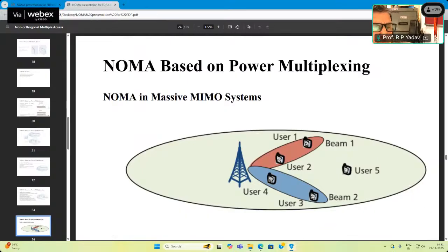And these MIMO systems help us in ensuring reliability. That means the signal will reach more reliably with the MIMO system, because the antennas are separated in space, and in time also you can separate them. So the multipath propagation and other things that distort the signal can be handled better if more such signals reach the receiver.